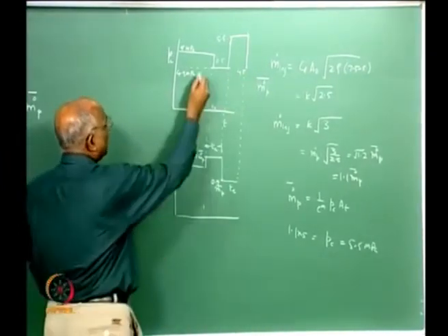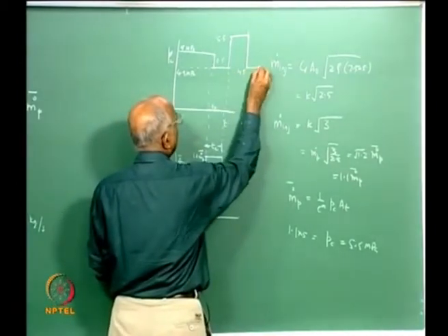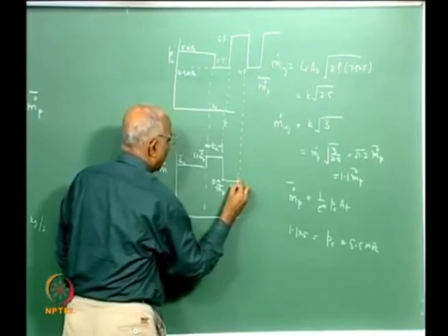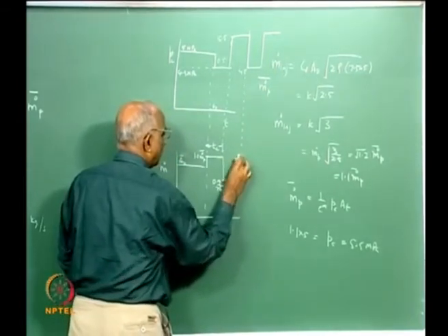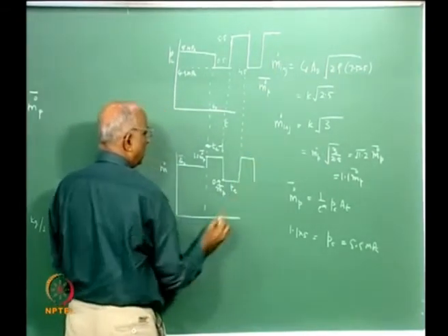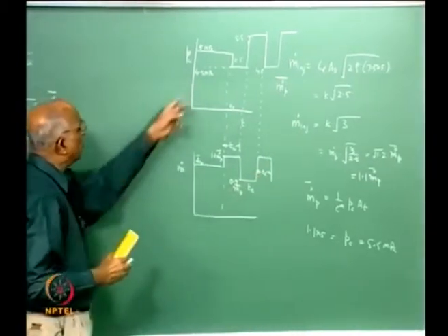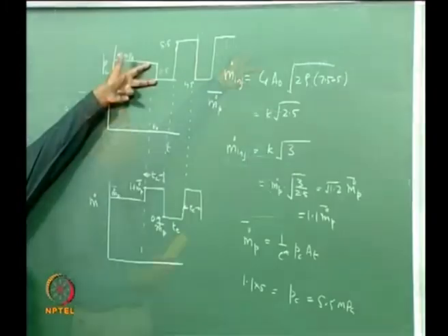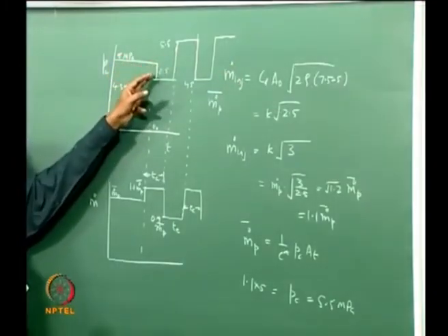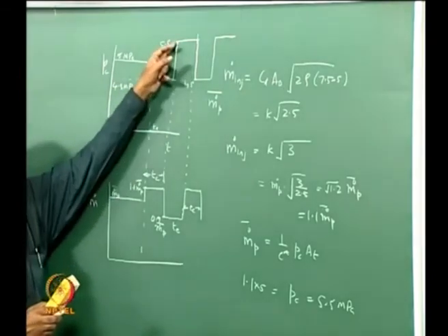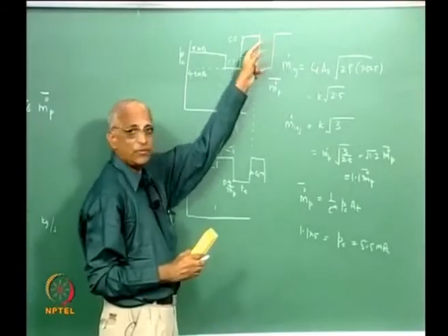And this sequence repeats: again it is 4.5, after a delay time it increases, and so on. It goes to 1.1 again, and from 1.1 it falls to 0.9, and this delay is Tc. So you find that a momentary drop of 0.5 makes the chamber pressure oscillate between 4.5 and 5.5.